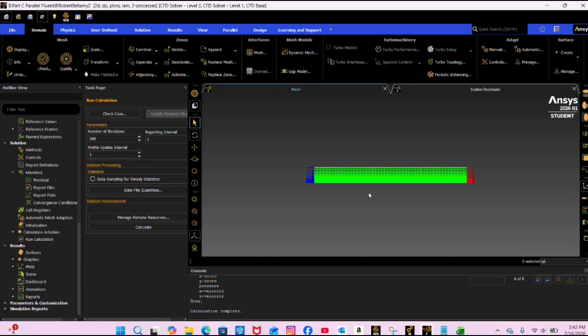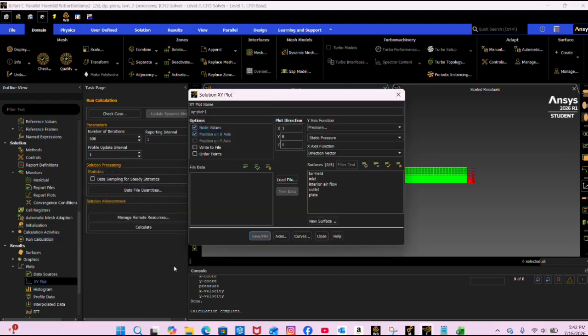And we do not want to do this, so we're going to go to plot, XY plot. And we are going to do 2 different plots, and you would use these 2 plots for your assignment. So the first one you're going to do, you're going to go here, the pressure, and you're going to make it wall fluxes. You'll keep this kind of the same for both. You do wall shear stress for this one.